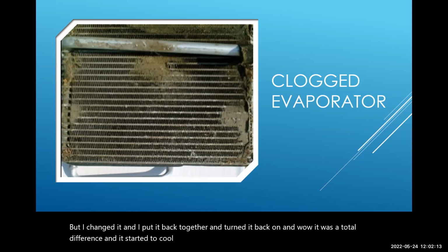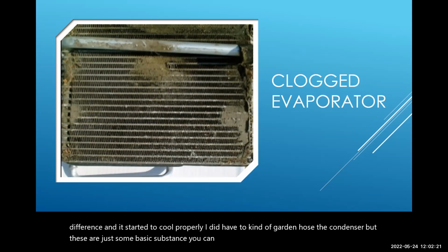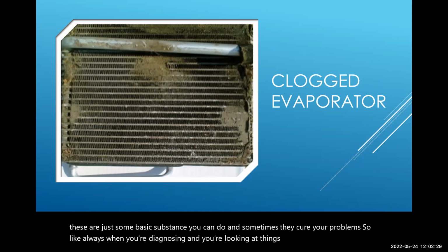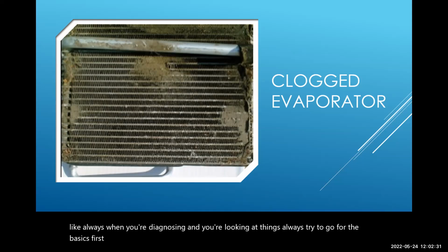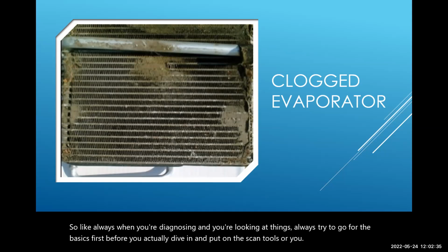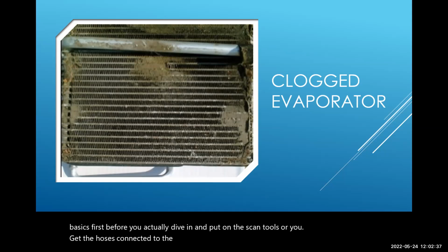I did have to kind of garden hose the condenser too, but these are just some basic steps that you can do, and sometimes they cure your problem. So like always, when you're diagnosing and looking at things, always try to go for the basics first before you dive in and put on the scan tools or get the hoses connected to the system. You want to look over the basics first before you go to the next step.